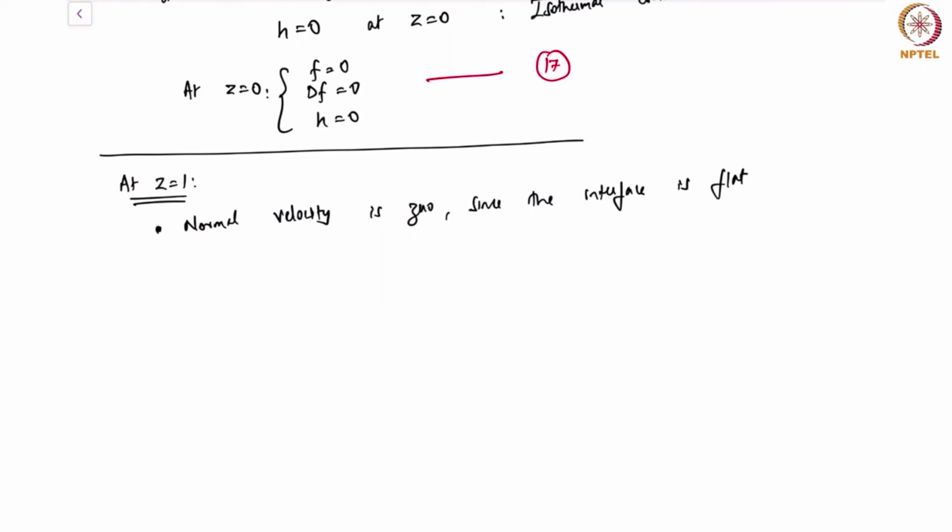Now one could also have undulations on the free surface, which has also been studied in the Marangoni instability context, but this will involve perturbations to the free surface height, and additionally we'll have additional curvature terms, and the Laplace pressure terms as well will enter the discussion. So we'll keep the analysis simple, and again the idea is to focus only on the Marangoni stress contribution.